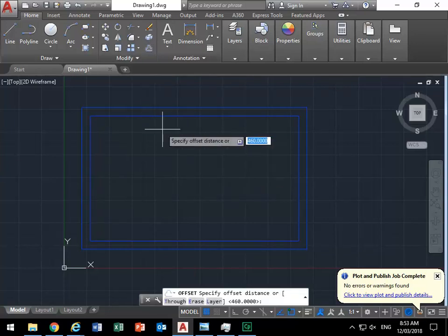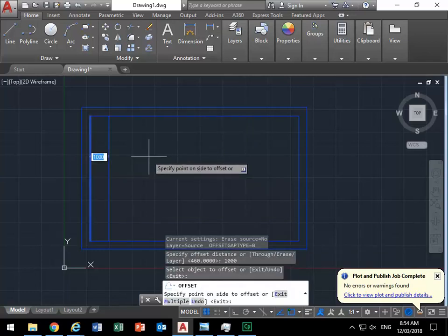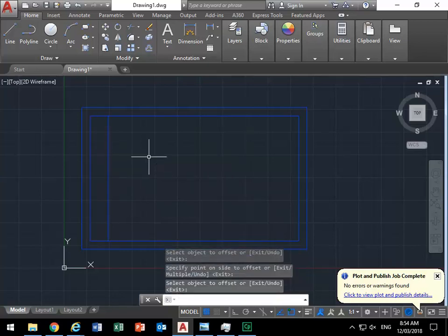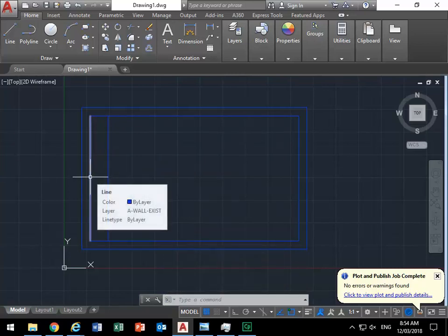post spacing. So again, just clicking on offset, and then always remember, if you're still struggling with offset, it'll always ask you for the distance first. So you just have to get used to always giving a distance after clicking on the offset tool, and then of course enter, and then I can select that line, click to the right, we know that's 1,000, and then the vertical distance, or the distance measuring vertically, is it's actually not dimensioned because it's centered.